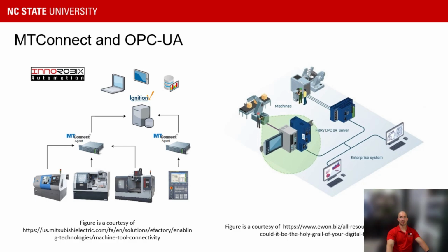The data types that can be transferred through those protocols are also predefined by specification and must completely correspond to the ISA 95 standard. It was shown that there is an issue when one is trying to communicate between different OPC-UA servers or even non-OPC servers. There have been several attempts to simplify the use of UA without specific proprietary software, but they require substantially more computational power than the MQTT protocol.